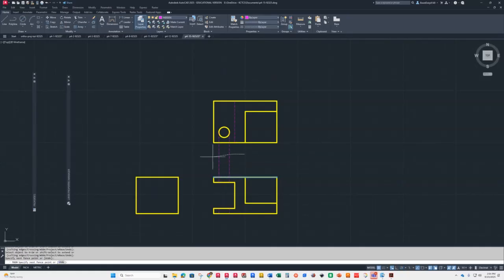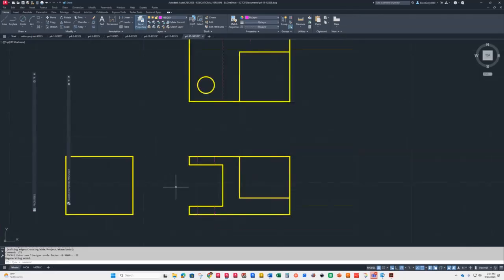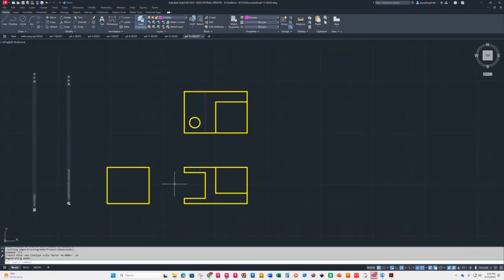That way you can just trim it out. And I'm going to slice trim that one. There we go. All right, so we just have our lines here. And since I changed my line type scale to 0.5, it looks a little better. So here, let's see what LTS looks like if I were to make it 0.25. Now that might actually be better. So depending on your settings, 0.25 or 0.5 might work better. It just depends. But it'll be less than 1 typically.